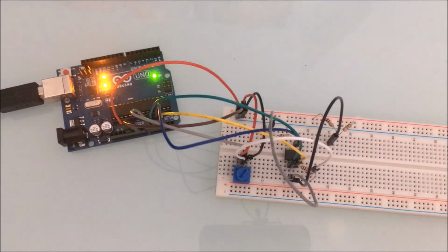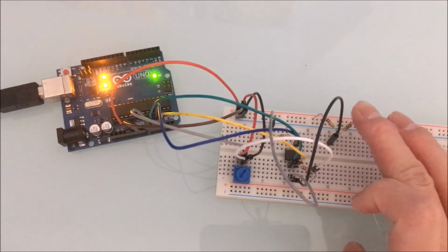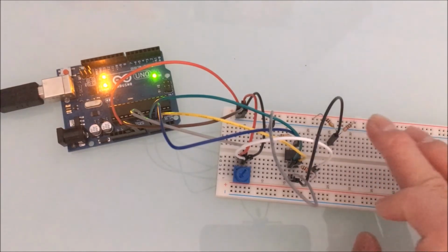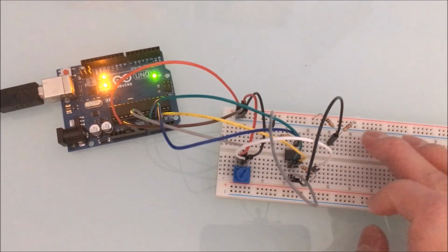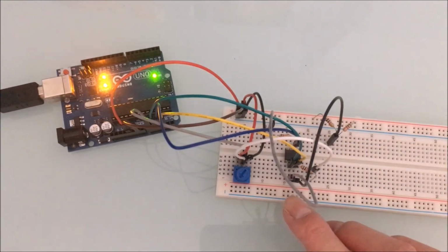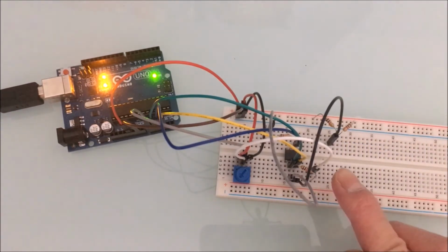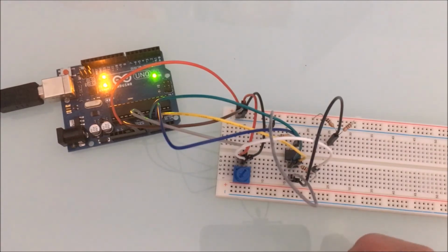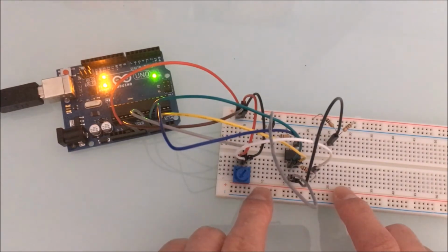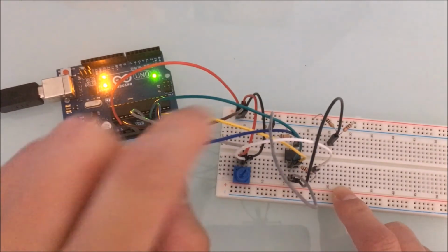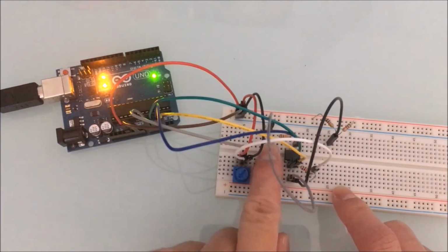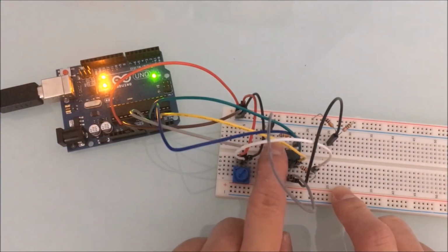So now here's the inverting amplifier circuit. Now a couple things to note is that over here we have a voltage divider, which is made up of two 1K ohm resistors, and that'll feed 2.5 volts into our non-inverting input. And that's going to be our new ground, quote unquote. And then we also have, bridging out from our inverting input, a wire that connects to this 10K ohm resistor, and that's going to feed into our output voltage.